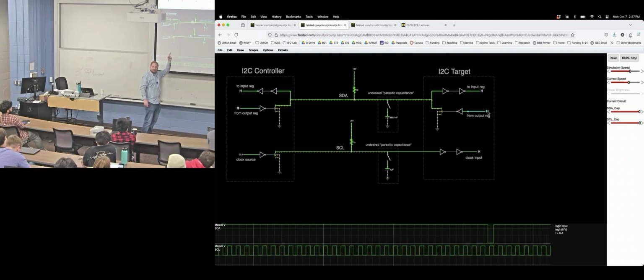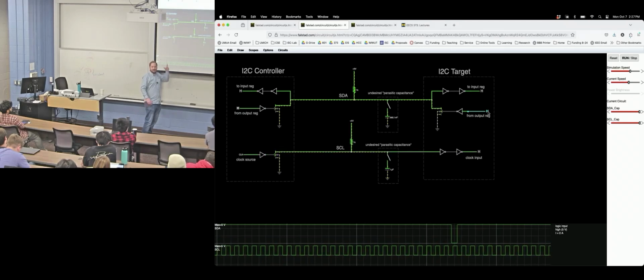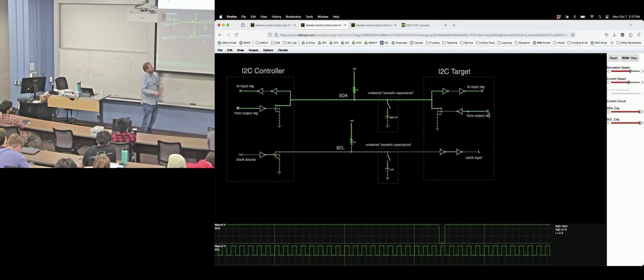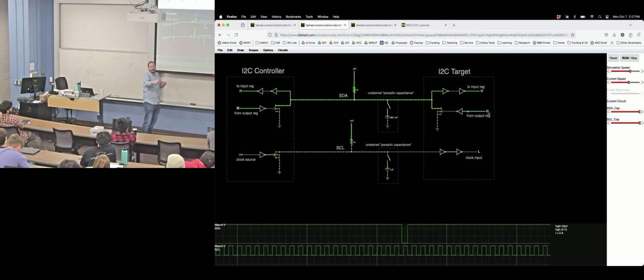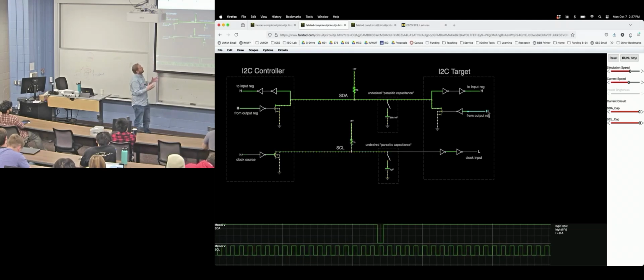They also gave you resistors as an option, right? And why in the world were they doing that? Well, this is why, because they felt like, okay, STM can differentiate itself in the marketplace by not requiring vendors to use their chips to also put resistors on the bus, right? Now the resistors are part of the chip themselves, and you can reduce your part count and size and complexity.